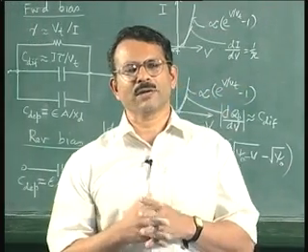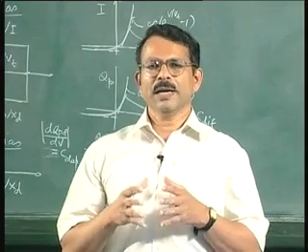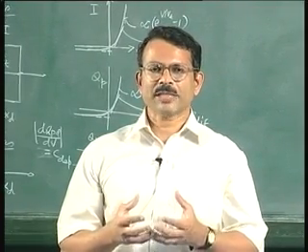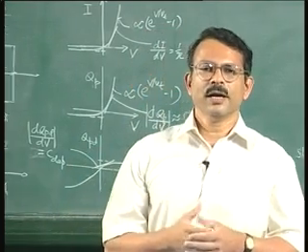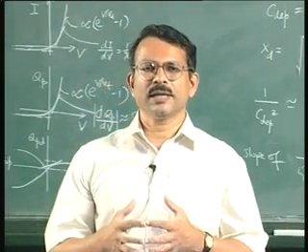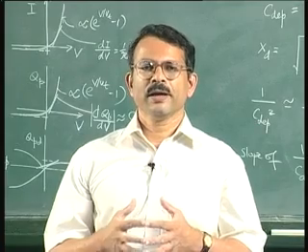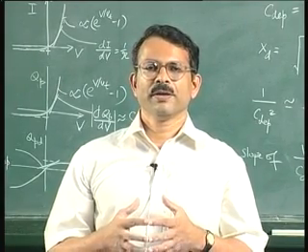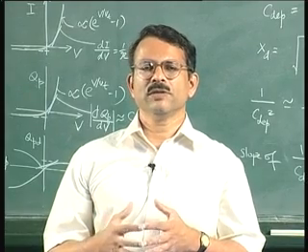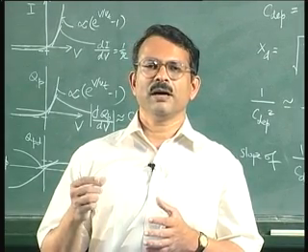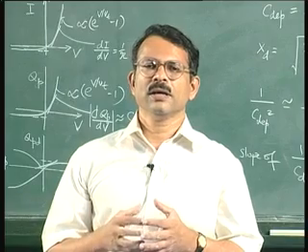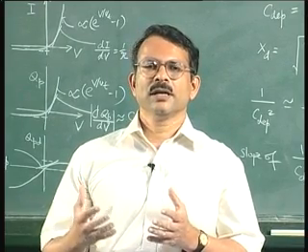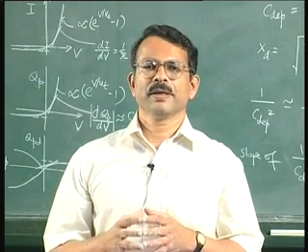Now since you have asked a question about the reverse characteristics, let me tell you another important aspect of the reverse saturation current. It is found that the reverse saturation current in a silicon diode doubles for every 10 degree centigrade rise in temperature, and for germanium diodes, in which the energy gap of the germanium material is less than silicon, in fact it doubles for as small as about 4 to 5 degrees centigrade change in temperature.